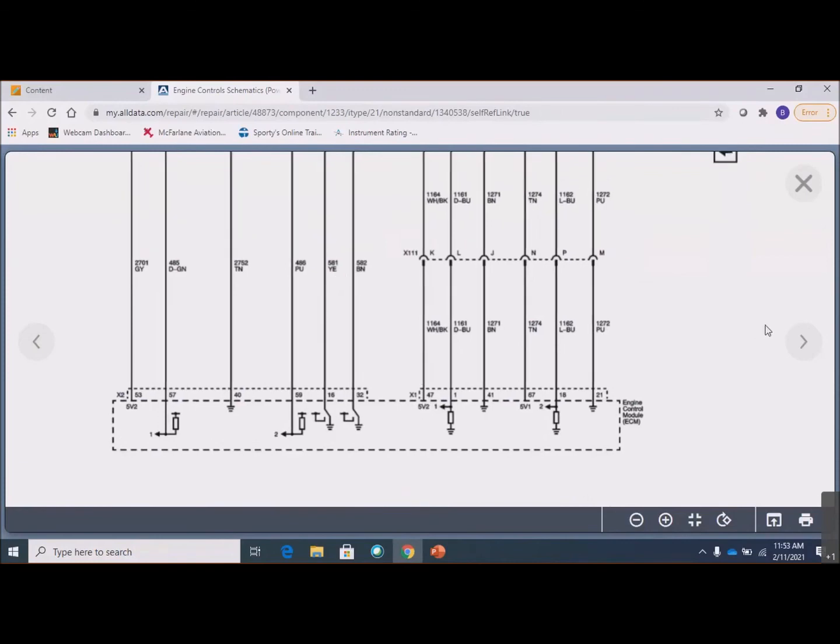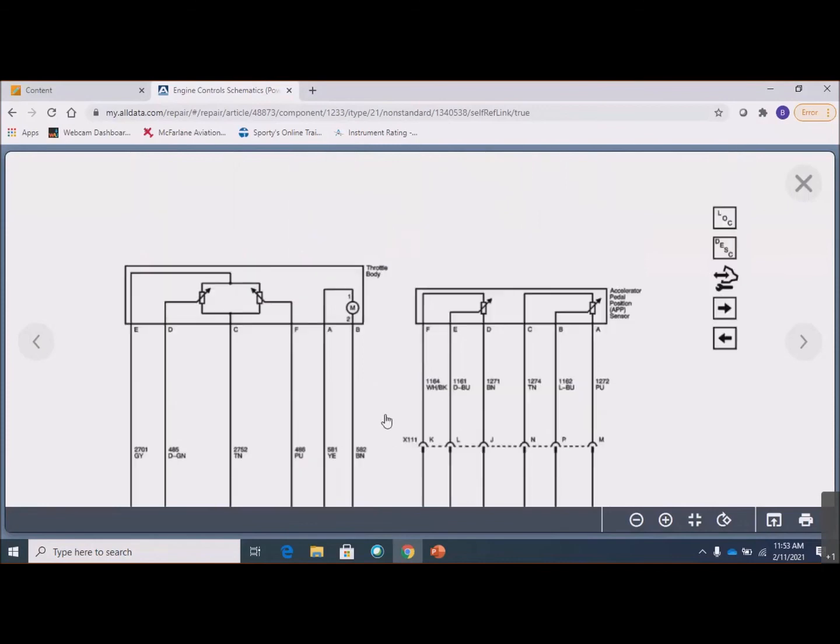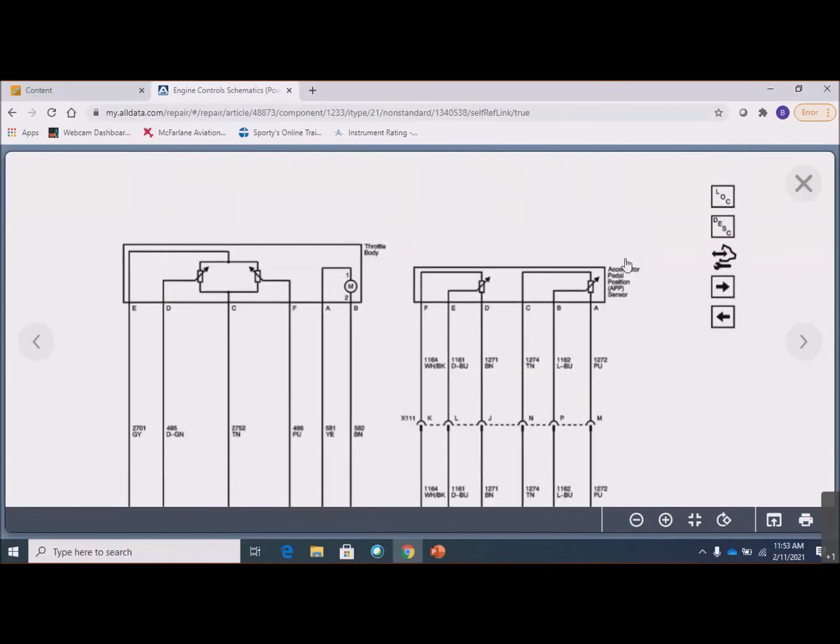That is more typical of what I've seen, right? So if these 2 here don't agree with each other, vehicle will not accelerate. If these 2 here do not agree with each other, vehicle will not accelerate. So this is all just safety stuff, so you don't have this unintended acceleration, vehicle screaming down the road out of control.